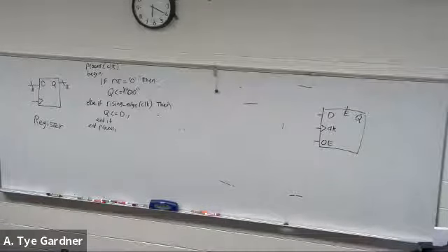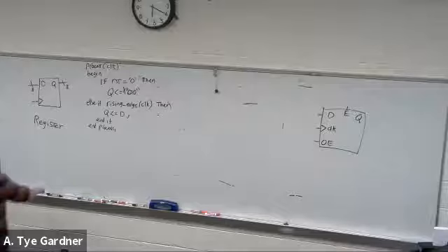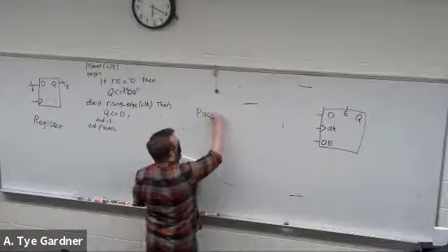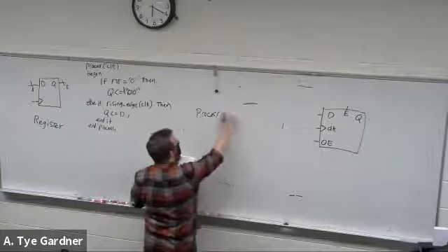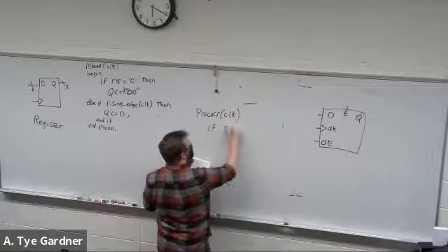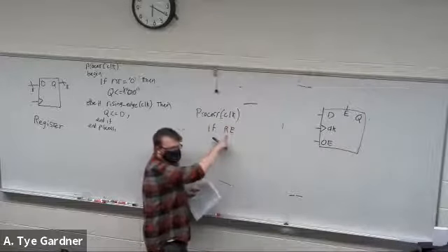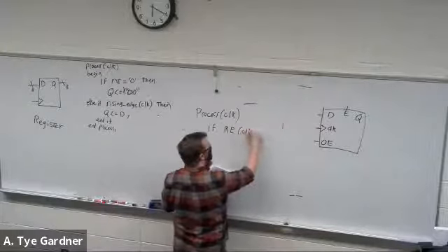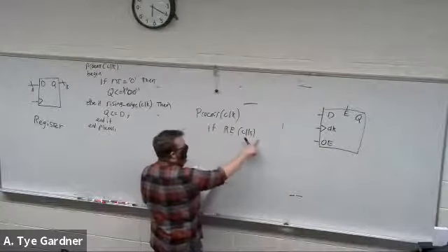You could say, I'm going to really shorthand this, process on clock if rising edge. You're going to see this abbreviation a lot, RE. I don't want to write out the correct command. If RE clock, I may even leave out clock in this one, right?